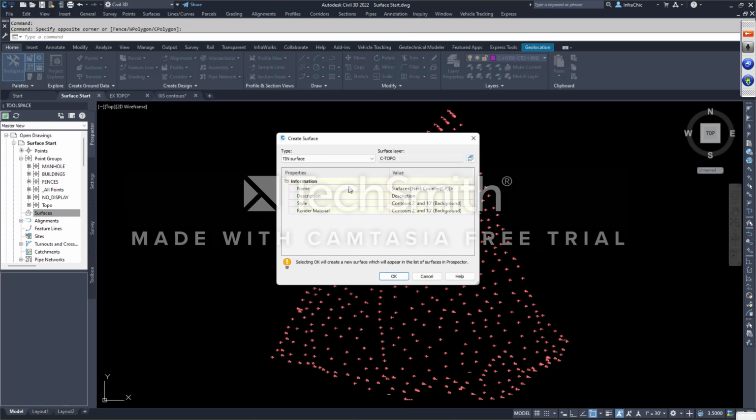And when I do that, I have two options for my surface type. In the Create Surface dialog, there are actually four. I can make a volume surface or I can make a regular good old-fashioned surface. Volume means I can compare in one surface to another, and the difference between the two is the volume, okay? So right now we're not doing that. We'll do that in a later time or a much further, advanced surfacing class, but that's what that is.